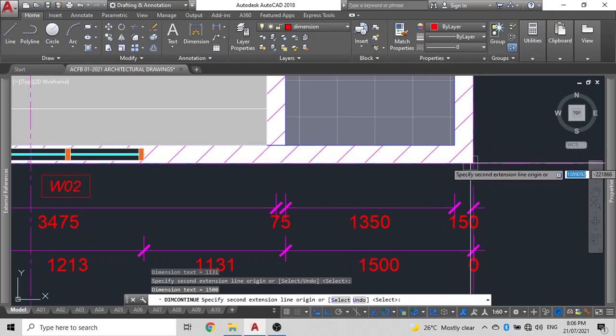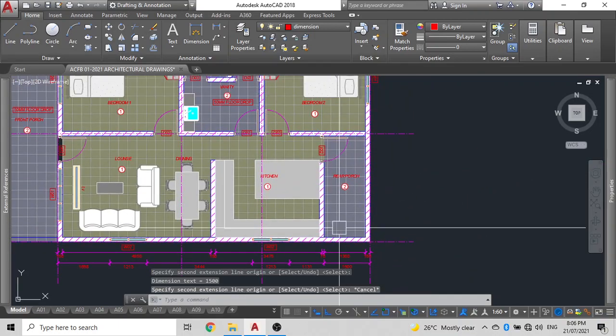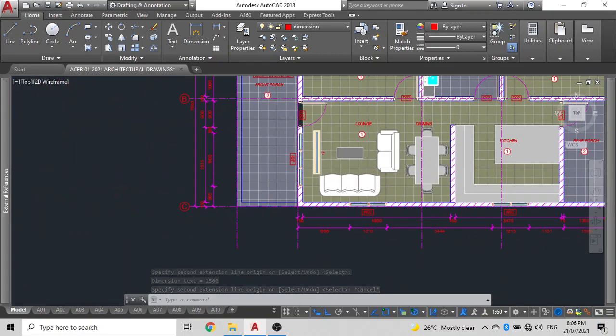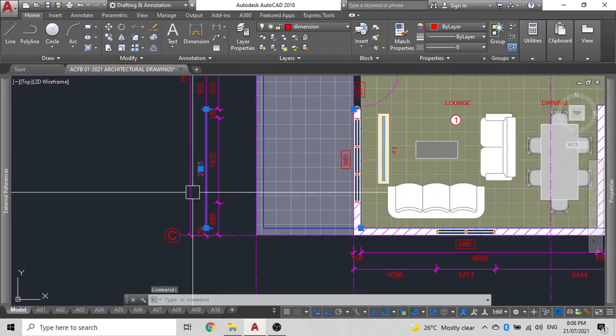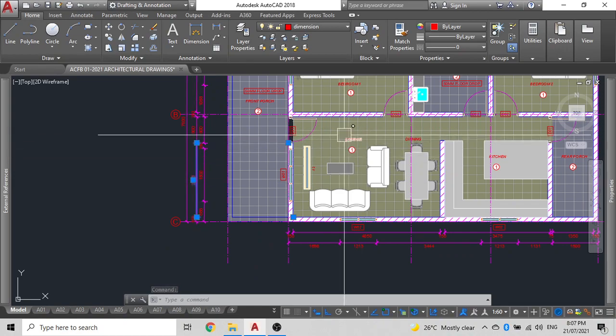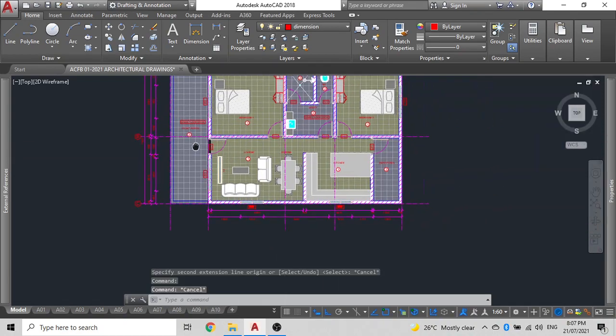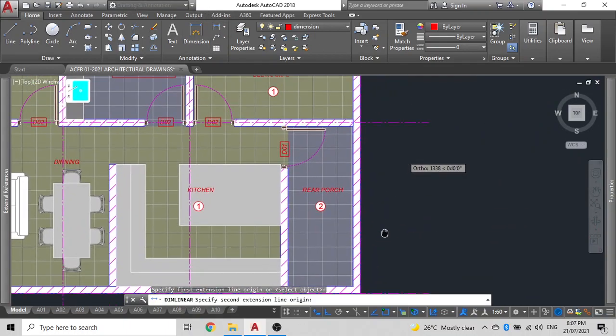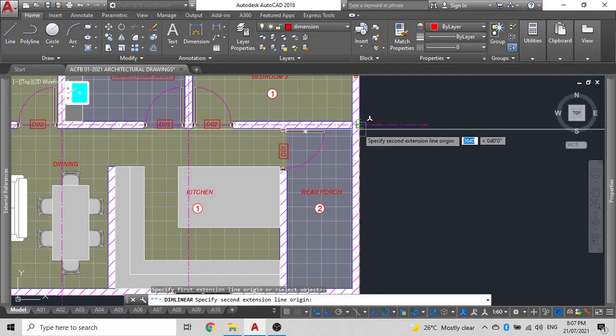And in that dimension, you can also get your porch's dimension. So now you know that the width is 1.5 for this rear porch, and the length of it will be 2515 millimeters. And then you add another 900 mm from the door. Or you can just add, let's just give a simple dimension over here. The more the merrier.